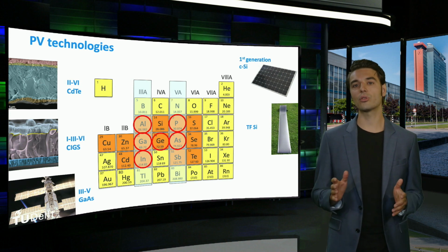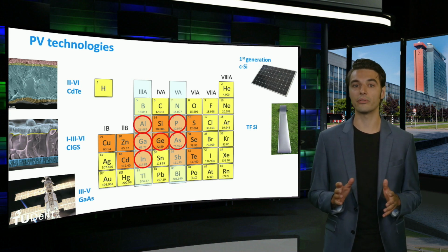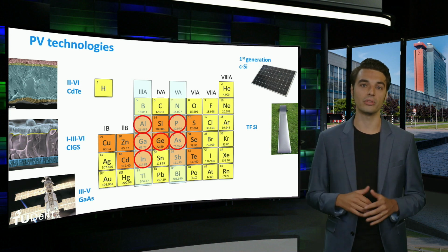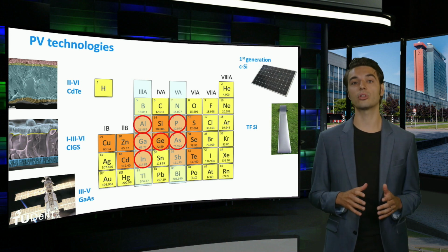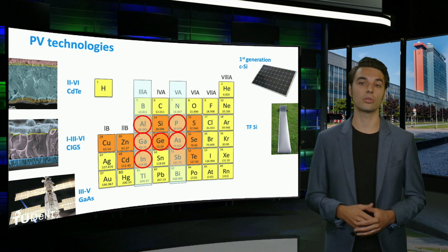As some III-V concepts use a crystalline germanium wafer as a substrate, it might not be considered as a real thin film PV technology. However, the III-V base absorber layers can be considered as thin compared to the thickness of a crystalline silicon wafer.